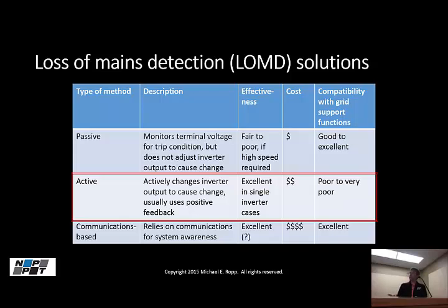If I wanted to do direct transfer trip to a feeder breaker, for example, then I can't just walk into the substation and stick a wire on the breaker. Right? There's a bunch of substation engineering. There are a bunch of requirements that need to be met. And you might imagine there could be more than one switch. I showed in that circuit there was the feeder breaker, a recloser, and a sectionalizer.